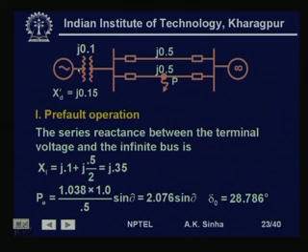So, first thing we will do is try to find out the transfer reactance between this point and the infinite bus. So, the transfer reactance between this point and the infinite bus is j0.1 plus these two in parallel. So, this becomes j0.25. So, it is j0.1 plus j0.5 divided by 2, lines in parallel, this is j0.35. So, what is the power angle characteristic that we will get?